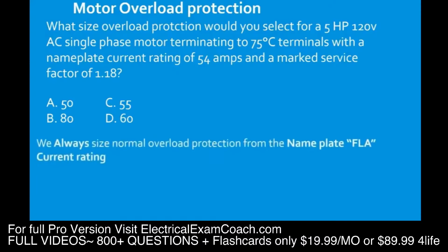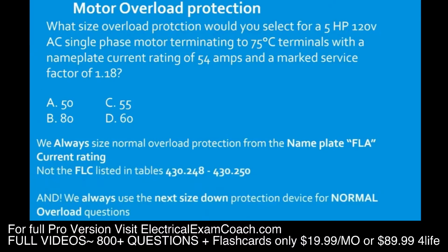So we head over. We always size normal overload protection from the nameplate FLA rating, not the FLCs that are listed in our tables. And we're always going to select the next size down.